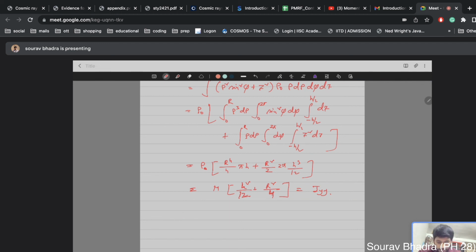For this case, for the xy coordinate, it comes from the symmetry, and Izx and Iyz are 0. These also come from symmetry, because it is not a laminar body, and we cannot write z equals 0 in this case, because all the z's are non-zero. So you will calculate Ixy, Ixz and Iyz, and you can see that all the values are 0 for the symmetry.